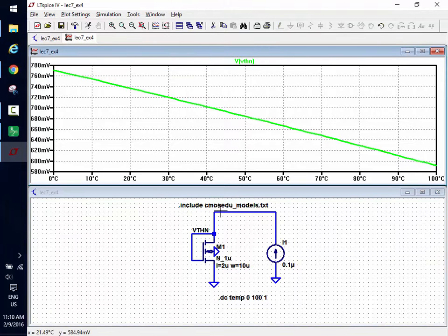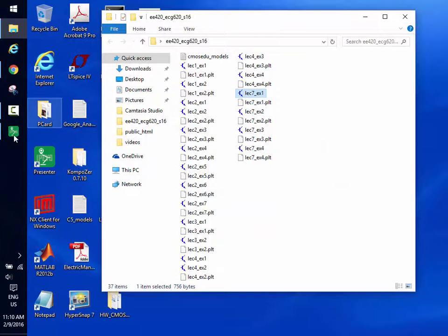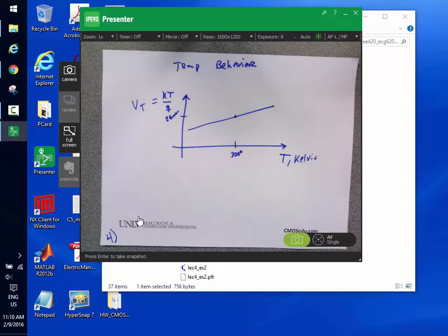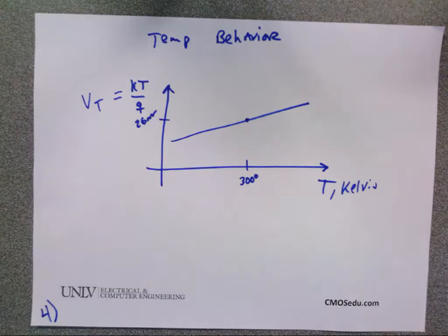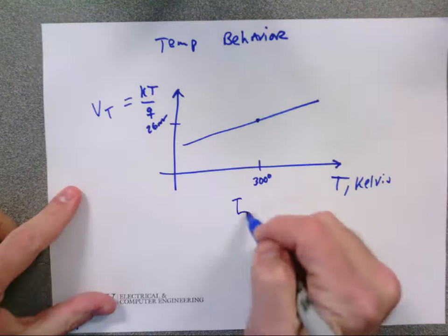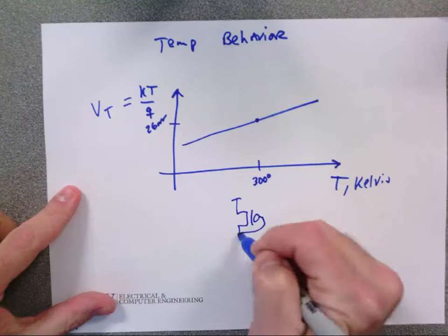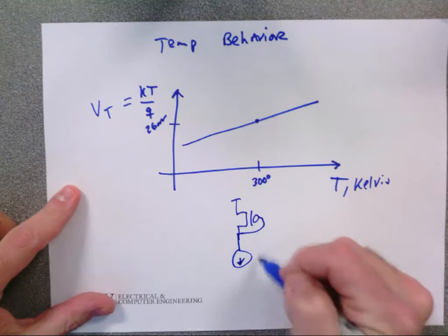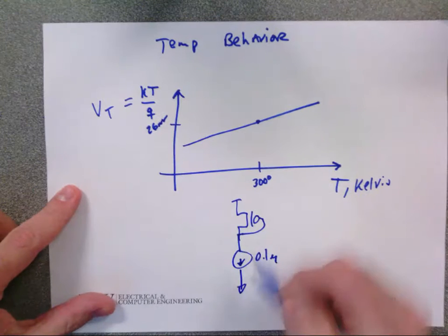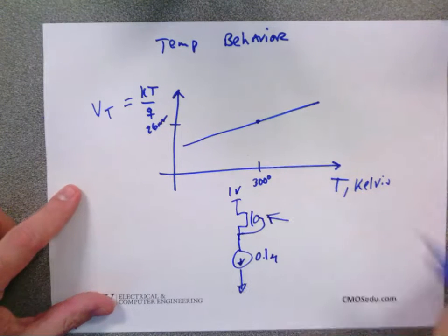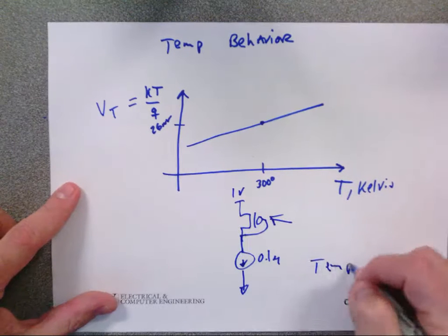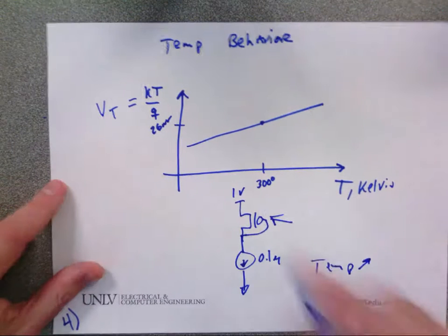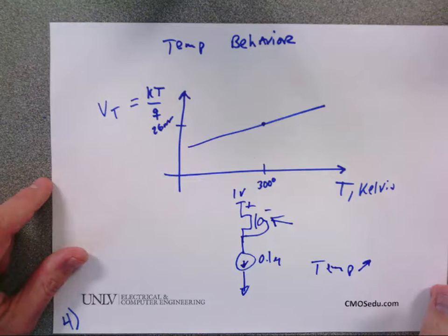No, because you put a VDD up here. So the VSG was decreasing, but let me show you. This is a good question. If I take the PMOS and I plot this voltage as temperature is swept, what happens to the VSG as temperature sweeps?